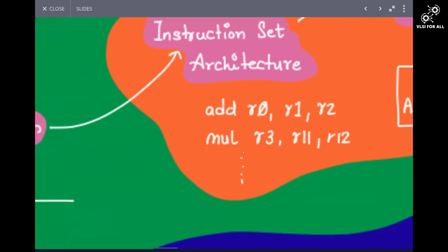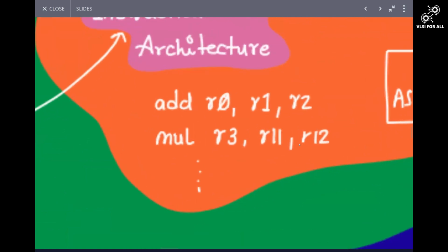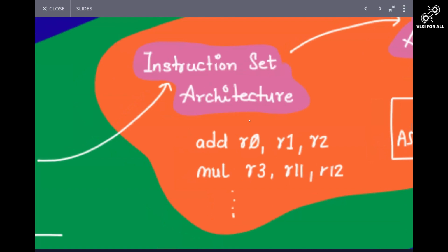Similarly, if you pass this multiplication instruction to the instruction pointer register, our processor will perform multiplication. And these are the operands that we are giving to the instruction. These are the set of registers, right? Your operands are stored in the registers. So that's what instruction set architecture talks about. Take your digital hardware. Now you give a provision to the software guy to tell him how to operate this hardware. Pass these set of instructions so that your program can be run on this hardware, right?